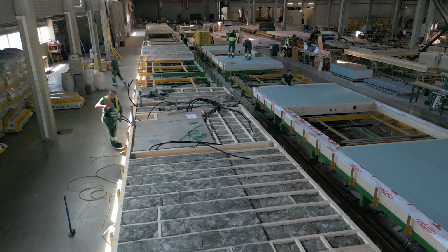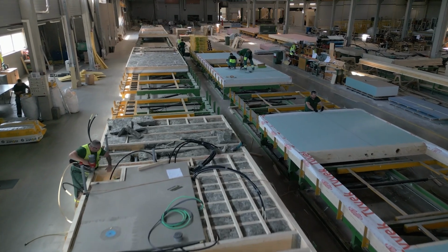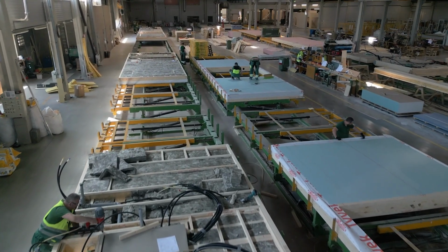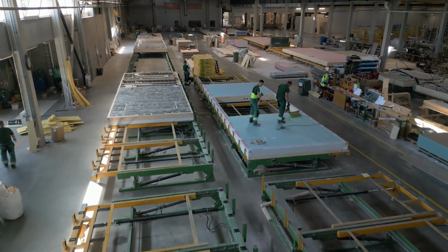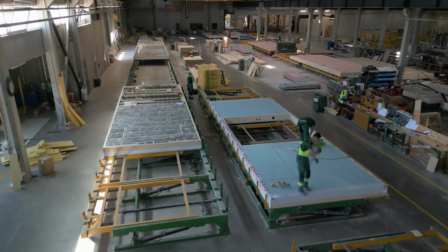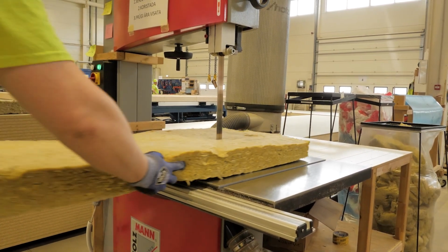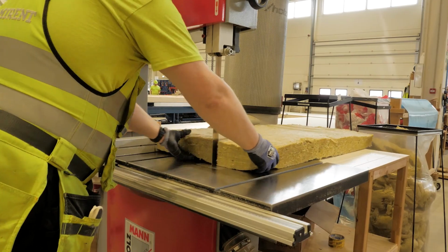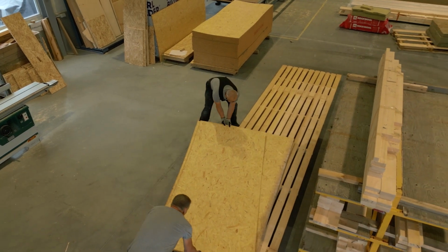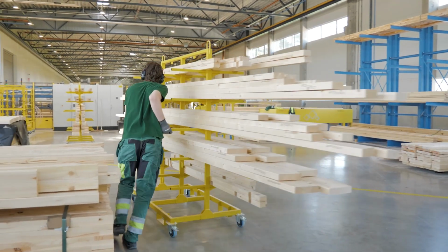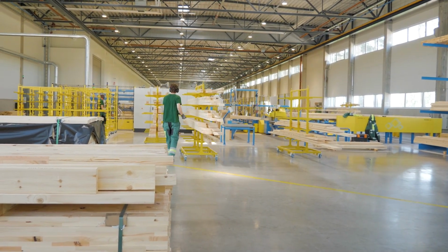The production process must be efficient, meaning that the entire production cycle must flow quickly and smoothly from start to finish. Each factory has developed its own specific logic for how materials and assembled components move precisely. However, the general principle is similar. Production begins with the preparation of the materials needed to make the elements. According to the project documentation, the wood for the frame, boards, and insulation are cut to the prescribed size. By using cut-to-size materials, the assembly of elements on the assembly table is therefore quick and smooth.